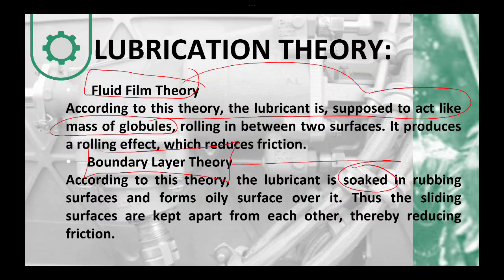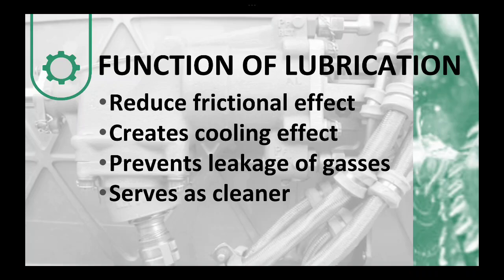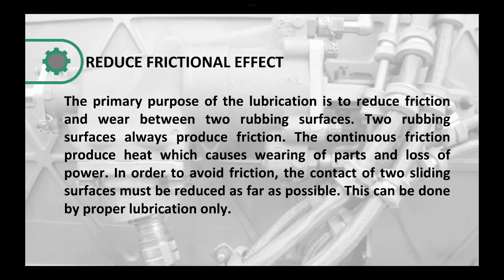Next, let me discuss the functions of lubrication. First is to reduce frictional effect. Second is to create cooling effect. The third one is to prevent leakage of gases. And the fourth, or the last one, is to serve as a cleaner. The primary purpose of lubrication is to reduce friction and wear. When you're rubbing your hands, you're making friction.